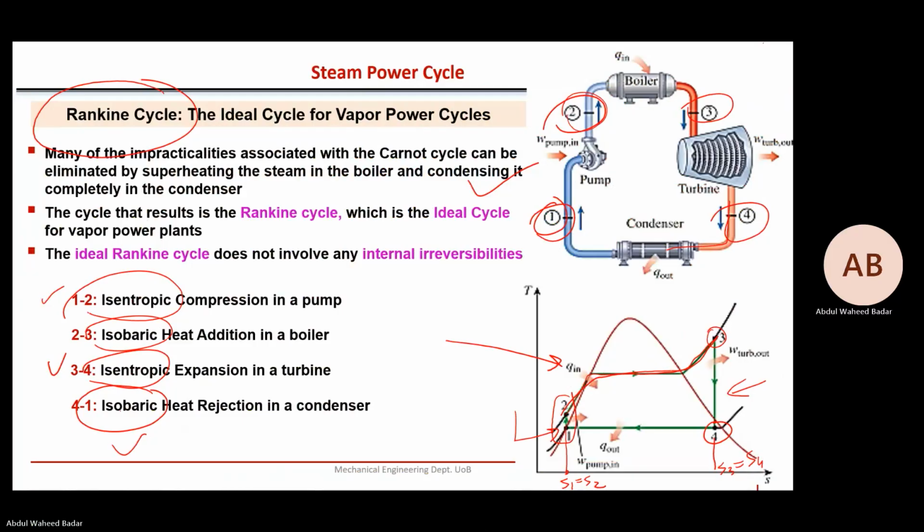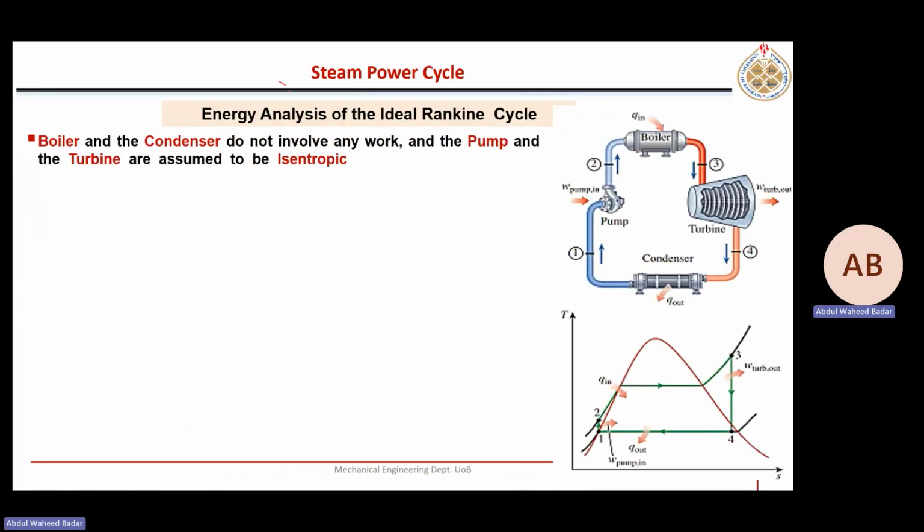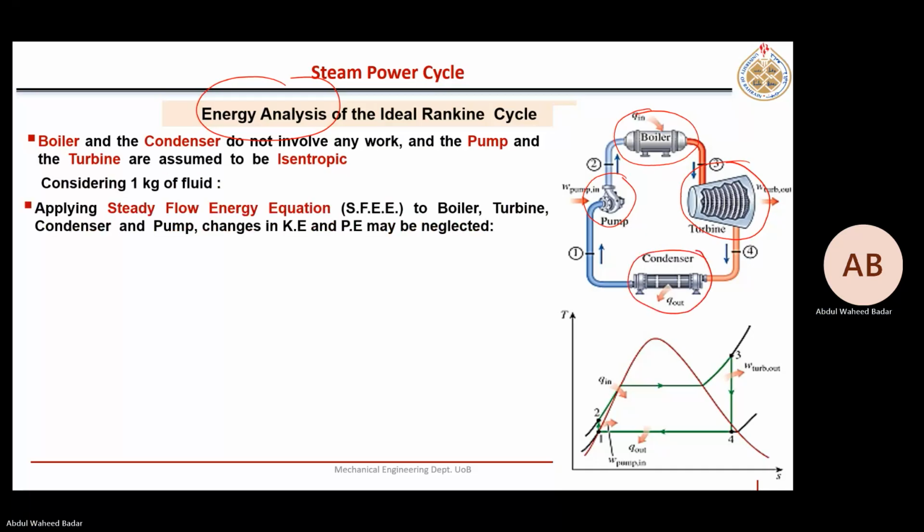Okay. So let's move on. Let's do the energy analysis. That is also something we covered already. Energy analysis means applying an energy balance for each control volume separately. Assuming 1 kilogram of fluid flow, apply the steady flow energy equation to each of these components, boiler, turbine, condenser, pump, by neglecting macroscopic kinetic and potential energy changes across these